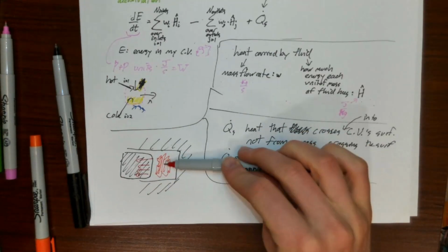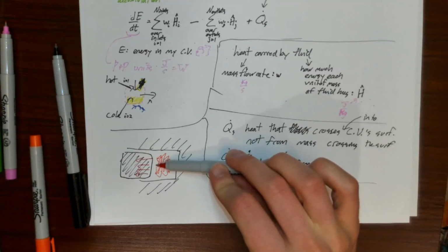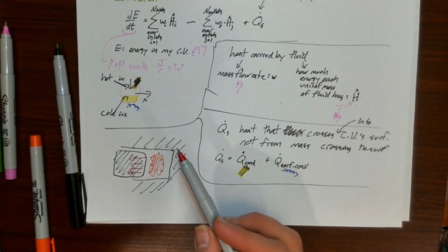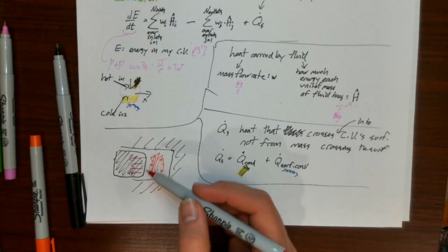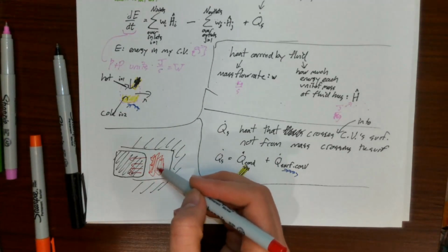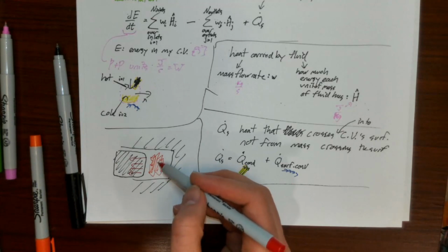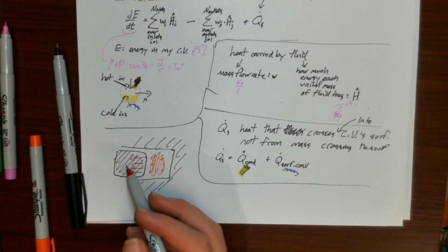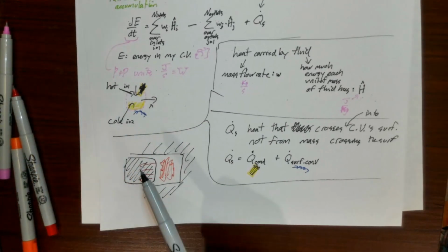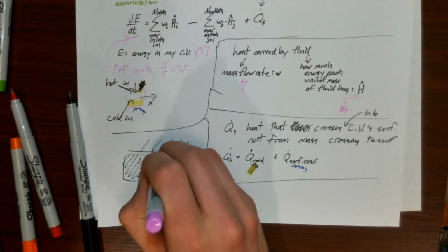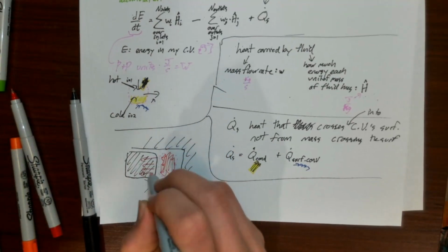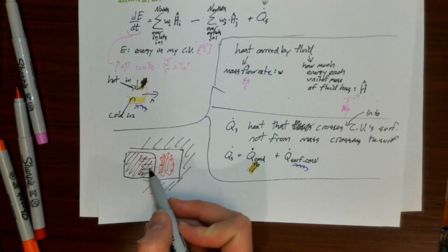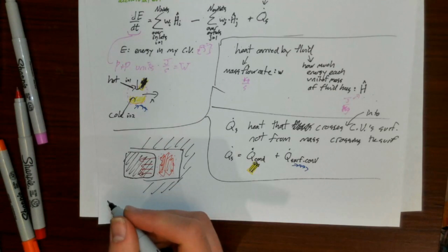And the work that these hot combustion gases do on the piston, that energy doesn't just appear out of thin air. The energy comes from a transfer of thermal energy of the combustion products into mechanical energy of the work, right? So if we have control volumes, for example, that are defined around things like combustion gases, we need to account for the work that those combustion gases do on the surroundings.